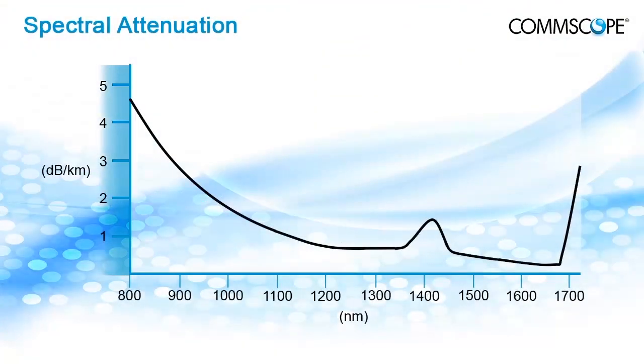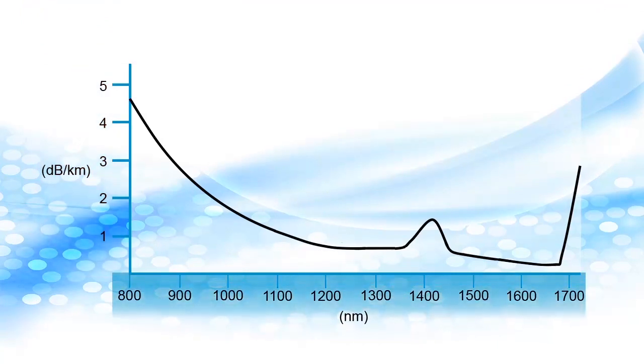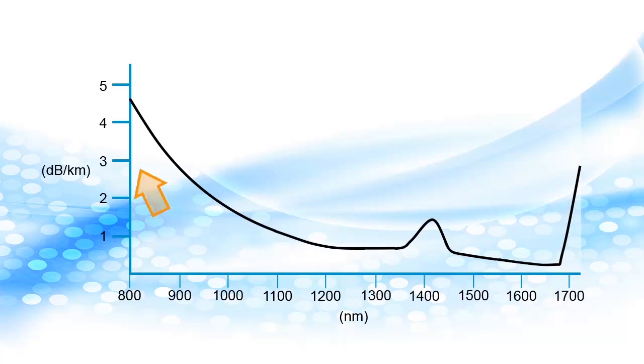The spectral attenuation is simply the loss characteristics built into the fiber optic cable given a particular optical wavelength. The lower the wavelength, the higher the spectral attenuation. You will see this applied to link loss budget calculations where we will take the worst case and apply those numbers for the end-to-end loss budget. Shown here is the fact that after the 1600 nanometer wavelength, the intrinsic attenuation actually goes back up. Therefore, it is not logical to say that we can keep extending the wavelength to achieve lower and lower losses.